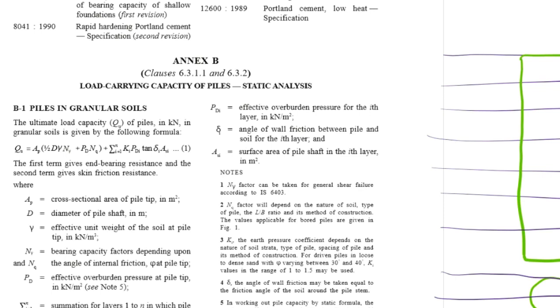Now we are applying some vertical load on this pile. When we are applying this vertical load, this load is taken by the pile and is transferred to the surrounding soils. So this pile will try to transfer this load through skin friction component like this and through end bearing in the given soil. The complete structural capacity of this pile will not be utilized if this pile is not resting on a very strong rock. That rock will behave like a footing for the column, and the column may fail as a structural member. But this situation occurs only when the piles are socketed into the rock stratum.